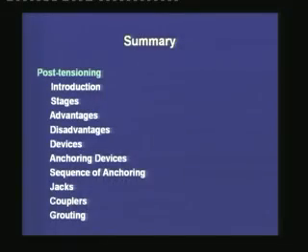The advantages of post tensioning as compared to pre-tensioning are: post tensioning is suitable for heavy bulky sections, especially if we do not have equipment to transport the heavy members, and if we have to cast the members at site, then post tensioning can be used to pre-stress the member. Of course, post tensioning can also be used for precast members where the members are made in a controlled environment, and then we of course need some transportation device to transport the member from the precasting yard to the site.